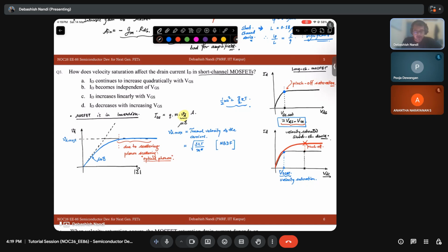Yes, sir. So the point is that at higher electric fields, of course your particle will have higher energy. E, the electric field, is your energy, and that will lead to opening up the optical phonons, and more optical phonons, one phonon is one scatterer, right? So more scattering, so your velocity gets saturated and your mobility drops severely. Fine, this is why your velocity saturation occurs.